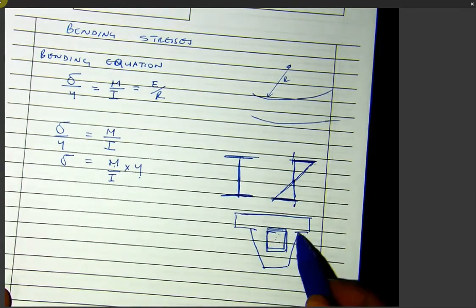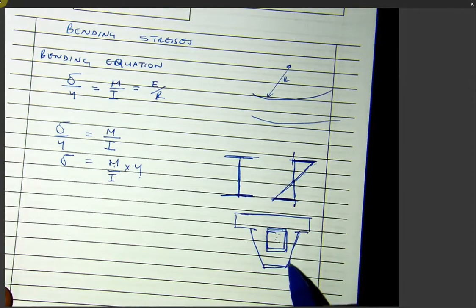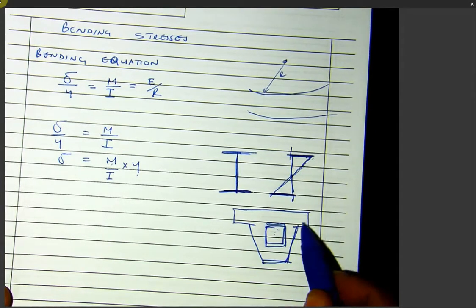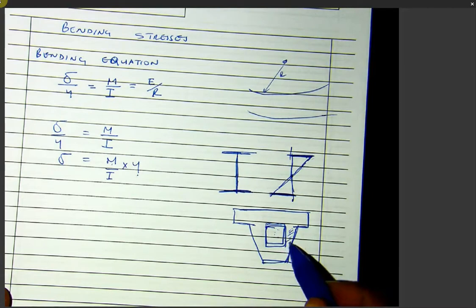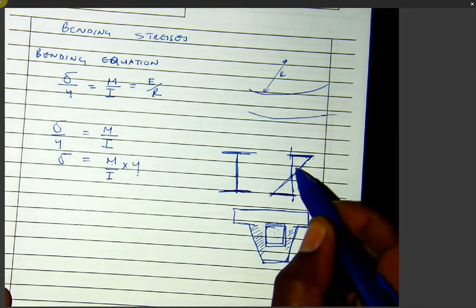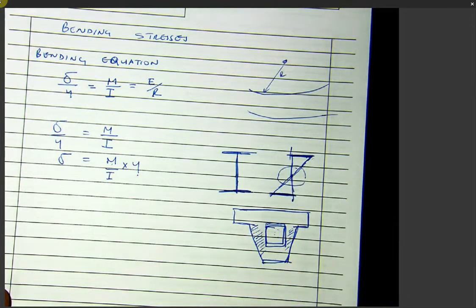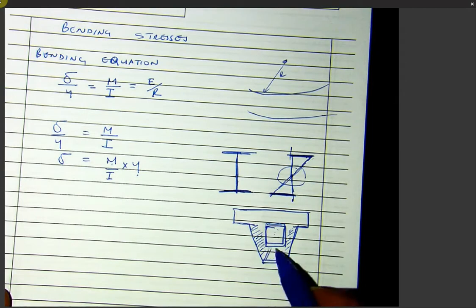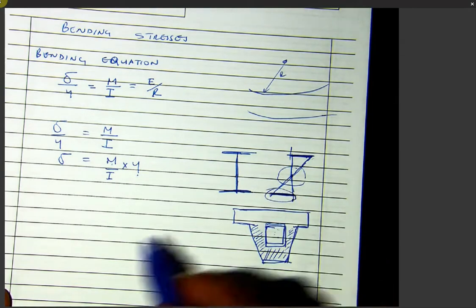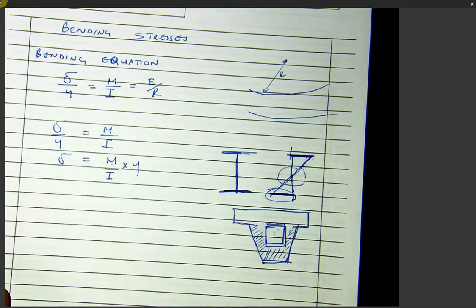So already we know the stresses. You work out the stresses, shear and bending stresses for that section, and then you work out can the remaining section handle the stresses around this area. Can this one, the bottom one, handle the stresses at this point? Because you don't want to over stress your section.